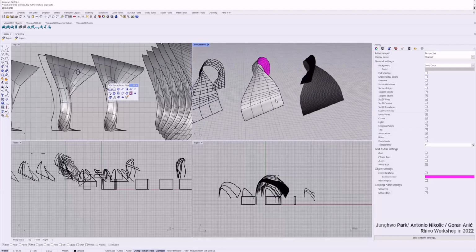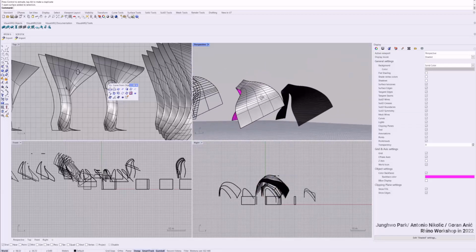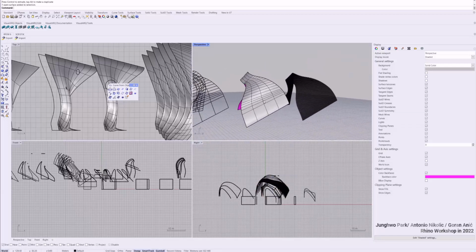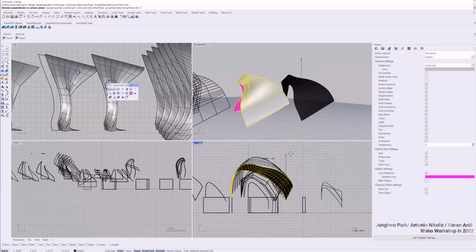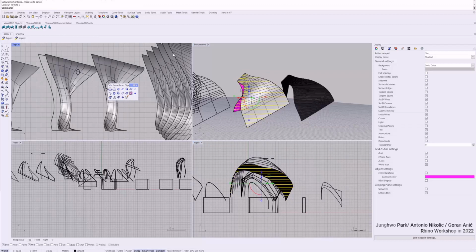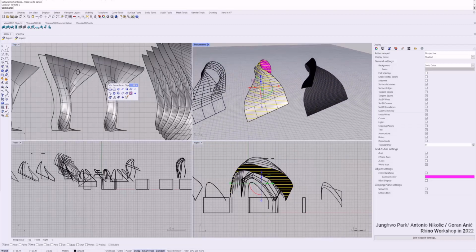Which could be interesting. For instance, let's say we have such a complex geometry imported into Rhino from whatever software, and I want to draw contours from here upward, every 1 meter let's say, and this one I'll probably extract as a facade.